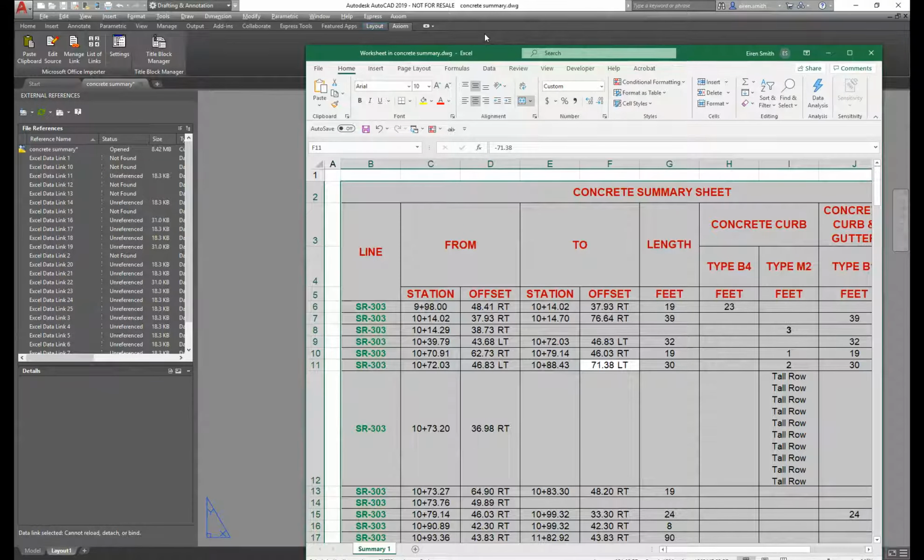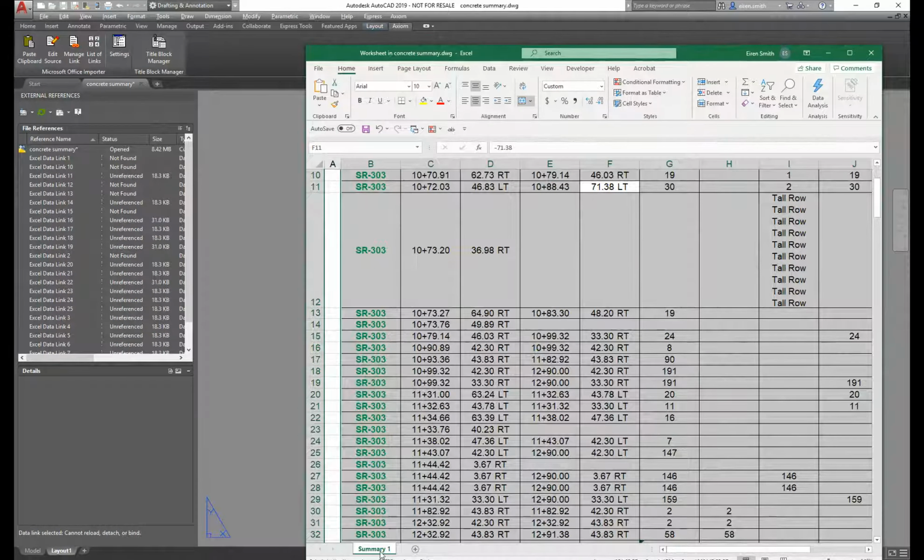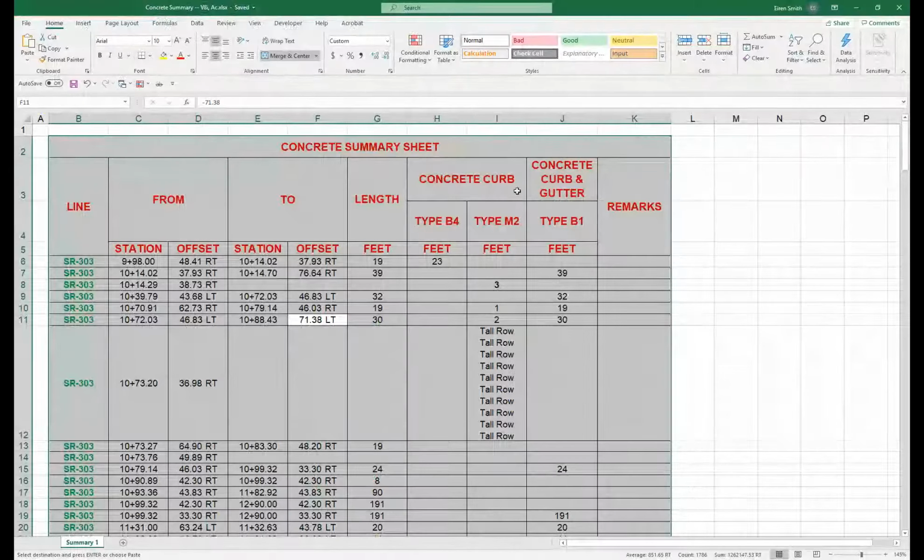The thing about an embedded spreadsheet is you're only going to get what you brought in, hopefully. It's a double-edged sword though, because if somebody else wants to change something in the actual spreadsheet that this data came from, well, that data is not going to come into AutoCAD. You're not going to get that. So in a group project environment, in a multi-person shop, which is most shops, it's usually better during the project to link to the spreadsheet where the data came from, not embed it into AutoCAD. There are cases where embedding is good and that's fine, but frankly, if you want to make changes in Excel, you don't want to have to go into that spreadsheet and get that to happen.